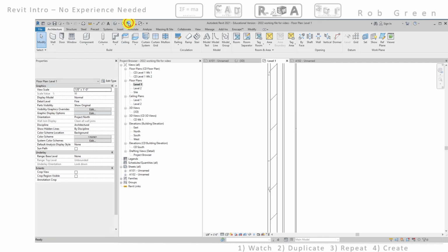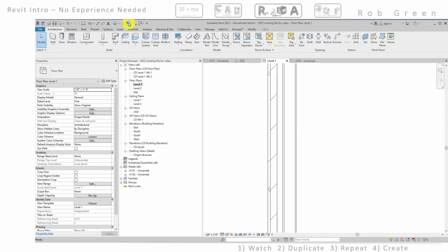So I'm going to toggle that right now, and you can see what's on my screen completely changed, and line weights are simply not visible anymore. They still print with a line weight, but they're not visible to me on the screen. And I will say that when I am modeling, I frequently like to have my line weights be turned off.